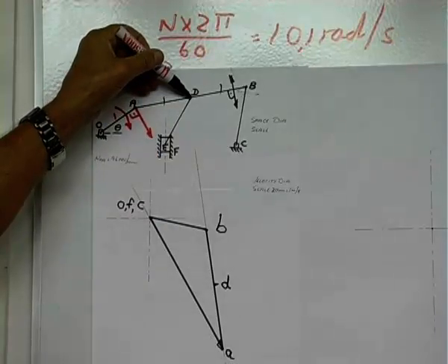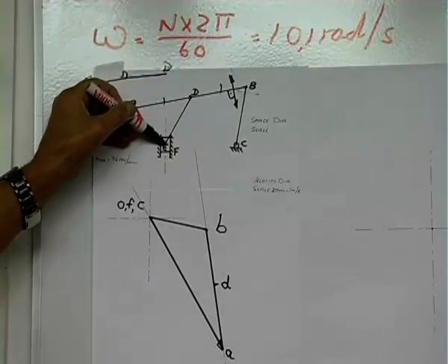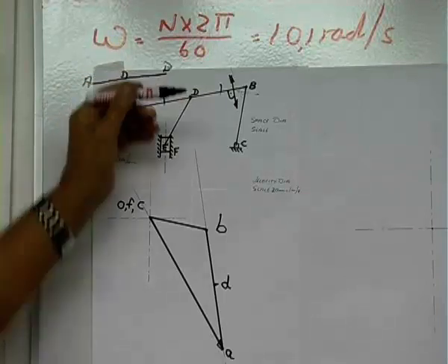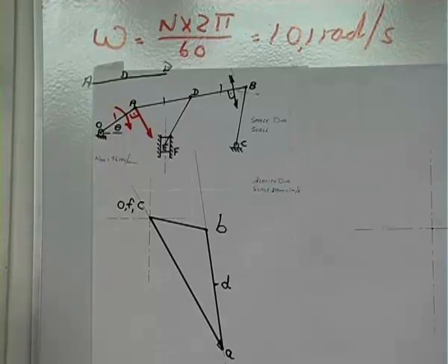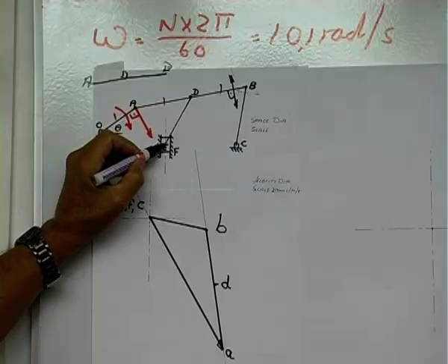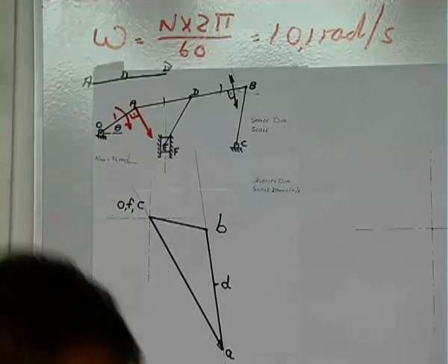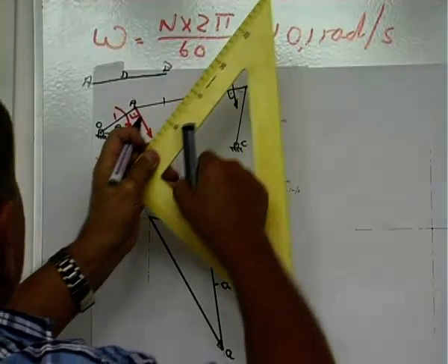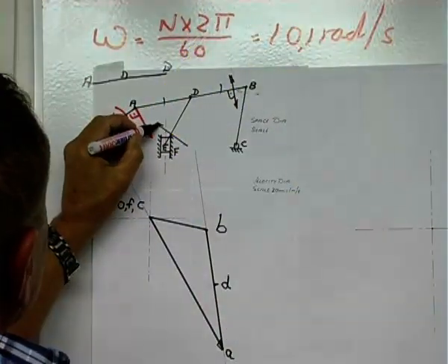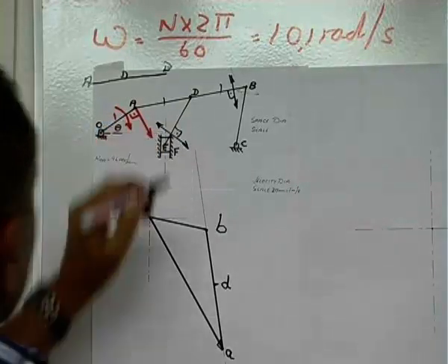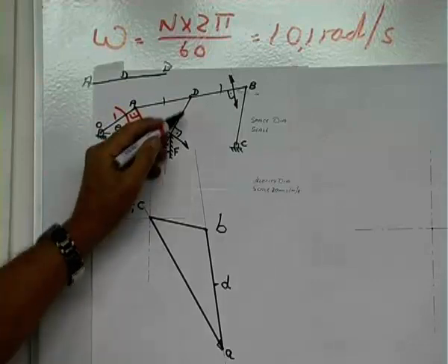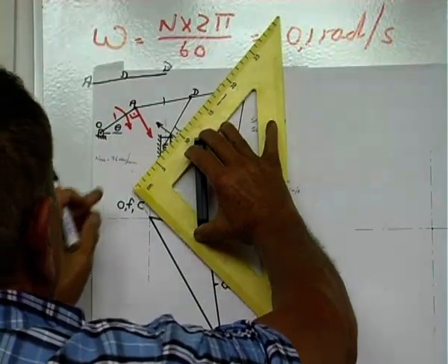Now you can go and stand on D, and you can observe the sliding block E. Ignore your own motion, your movement, né? Only concentrate on the possible motion of E relative to D. And again, it will be perpendicular to that link. So through D, we can draw that line.